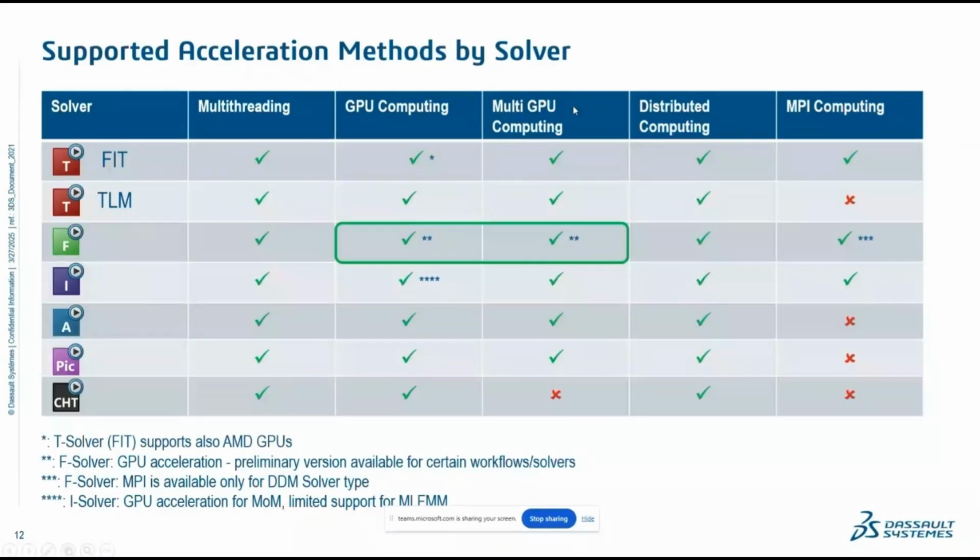As a summary, we try to support all the solvers in CST through GPU. With that, now frequency domain solver, especially the domain decomposition solver, now supports GPU and MPI computing. This is in the preview stage though, but it's already available with the software.